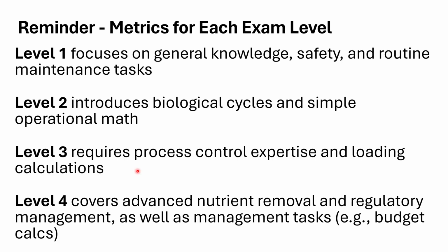Okay, it really will. Level 4, you're talking regulatory issues, nutrient removal, and management tasks like putting a budget together, budget calculations. How much chemical do we need to buy, and what's going to cost us for this process if this is our wastewater and this is our disinfection process? How much do I need to set aside to run a pump station if a pump has these characteristics, and this is what the cost of electricity in kilowatt hour is? And this is how long the pump's going to run over a year. They can ask you, what's it going to cost to run the pump for a year?